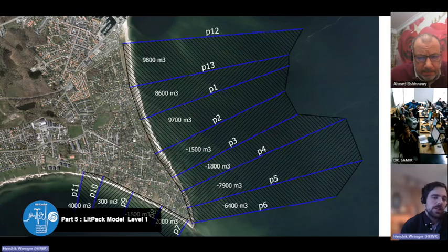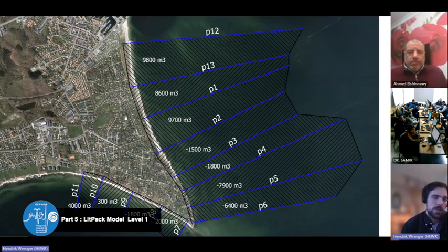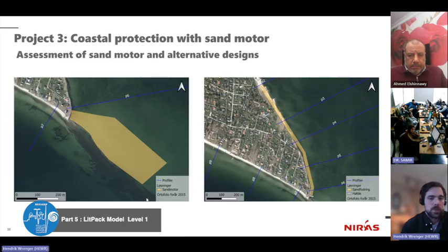And then you can still see that the balance of the potential transport will be minus 1,500 cubic meters. I don't know the time unit now. So there will be some erosion in that area if the material is available. If there's a non-erodible layer, there will not be any erosion. So it doesn't make sense to model this with a coastline evolution toolbox. Here material will be deposited. So basically from that post-processing, you can do a lot of sediment balance calculations. And that's the last slide.